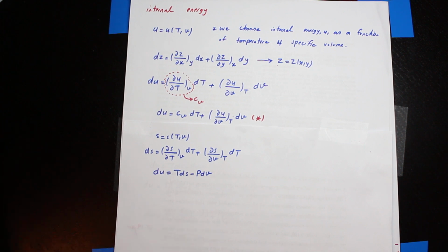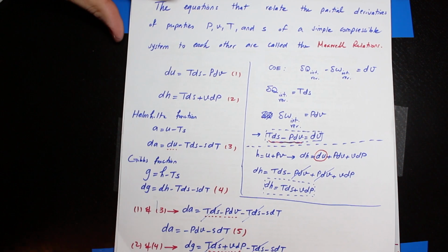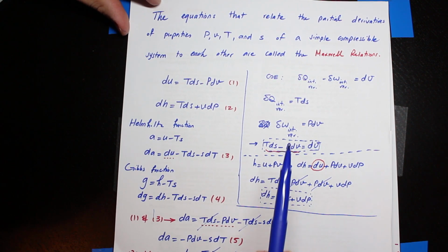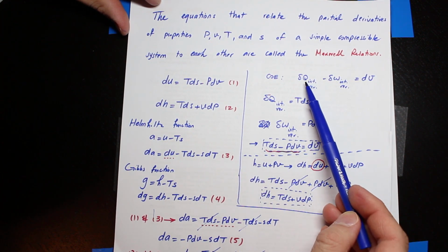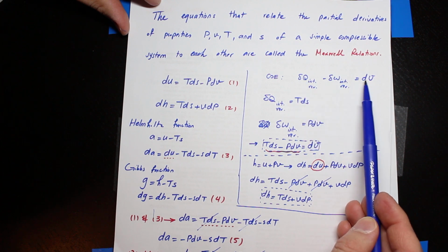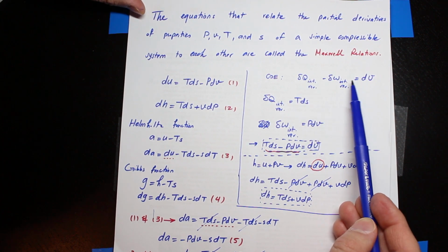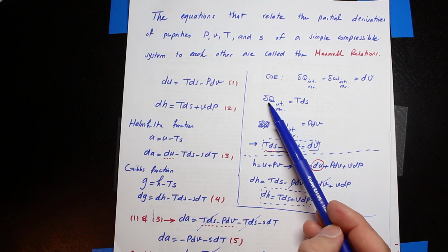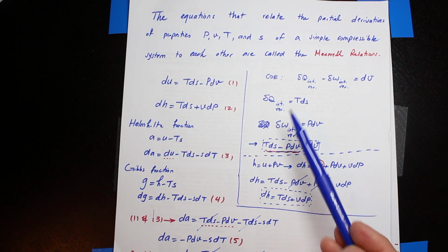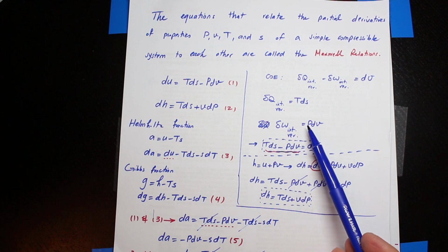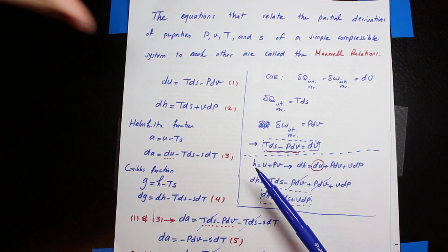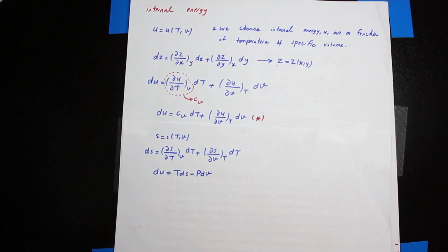When we discussed Maxwell relations, I utilized the conservation of energy on a differential system, and then for an internally reversible condition, dq was equal to T ds and dw was equal to P dv, so we could come up with this correlation. I'm using that once again here.